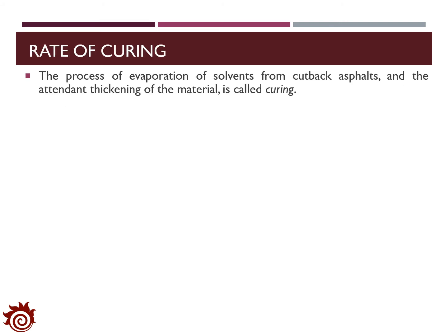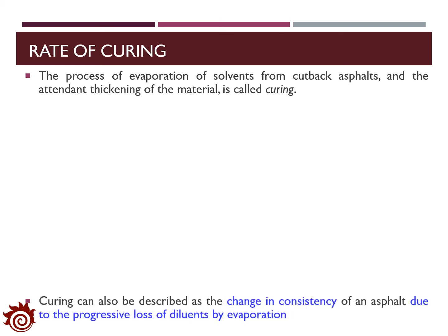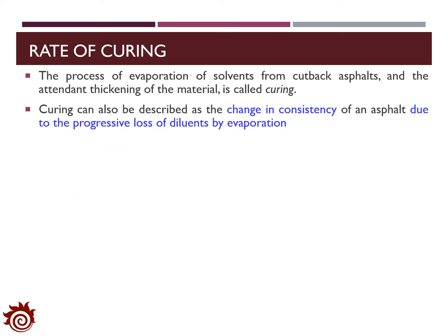In asphalt cement, curing is the process of evaporation of solvent from cutback asphalt and the attendant thickening of the material. Usually, curing can be described as the change in consistency of the asphalt cement due to the progressive loss of diluent by evaporation.